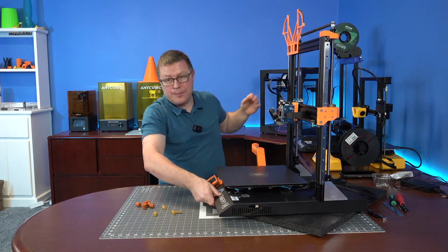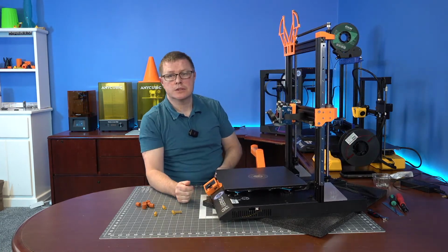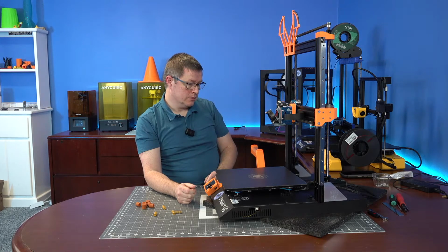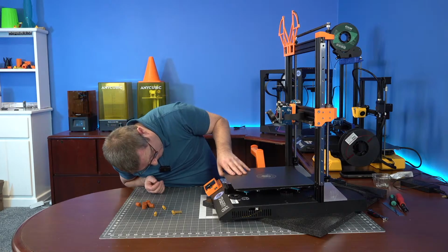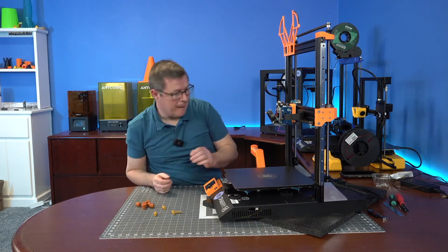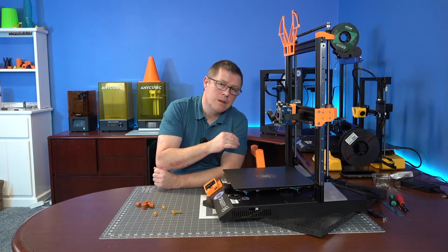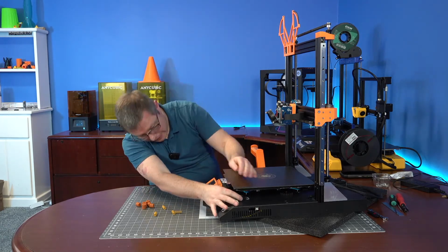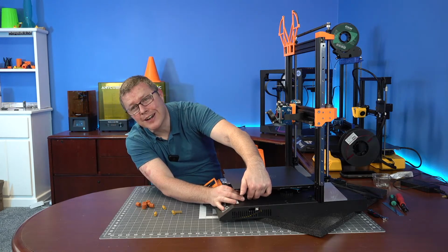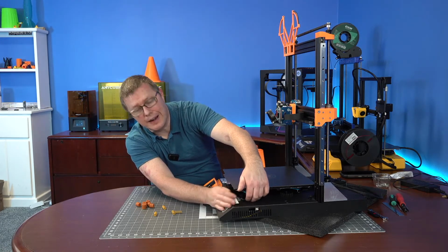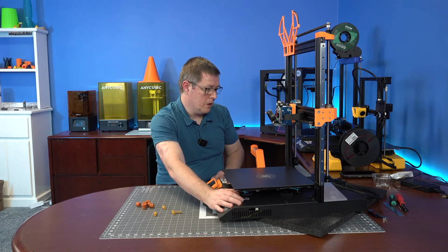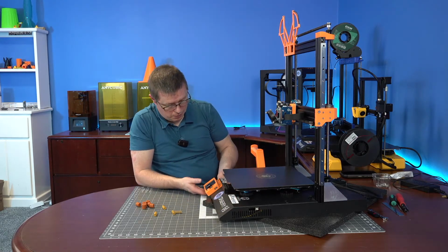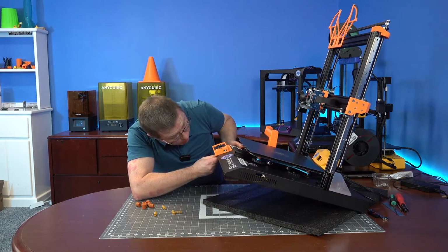So Monty says they had issues with a nut below the bed hitting the heater pad, so you have to be careful with the silicone spacer height. And Drew says the shorter one is for where the bed heater cable connects on some printers, like a CR10S Pro V2. I didn't hear all of that. Sorry. Monty says, I've had problems with the nut below the bed hitting the heater pad, so you have to be careful with the silicone spacer height. Okay. What nut? Oh, okay.